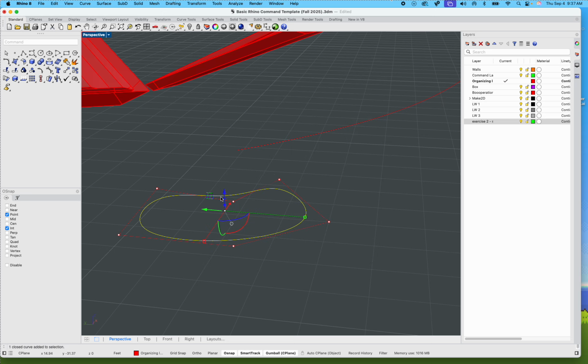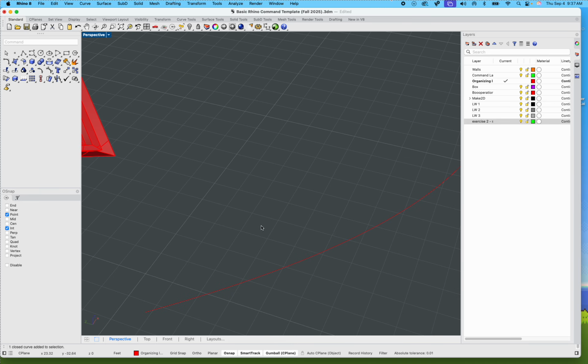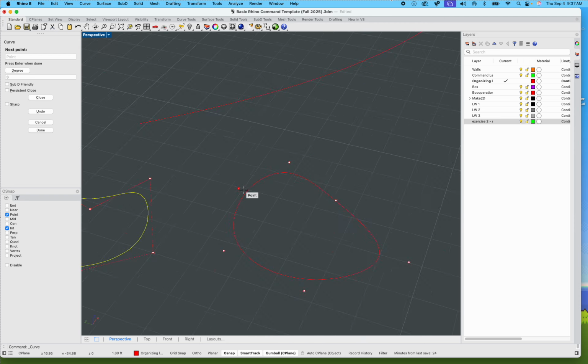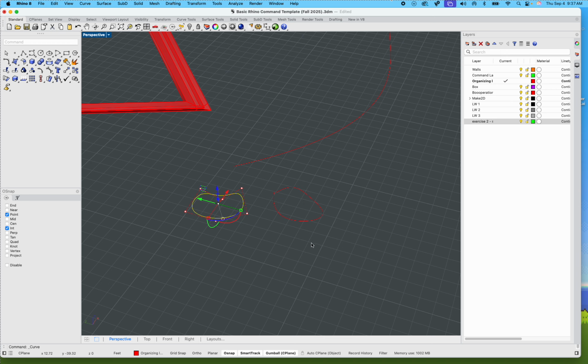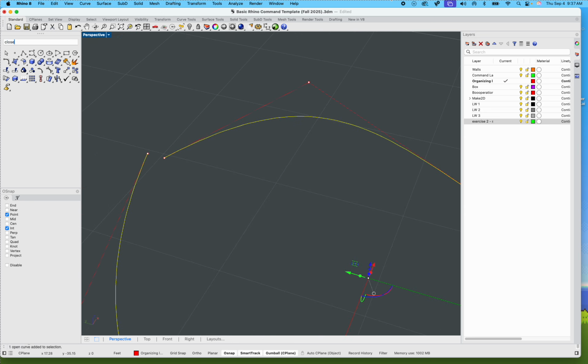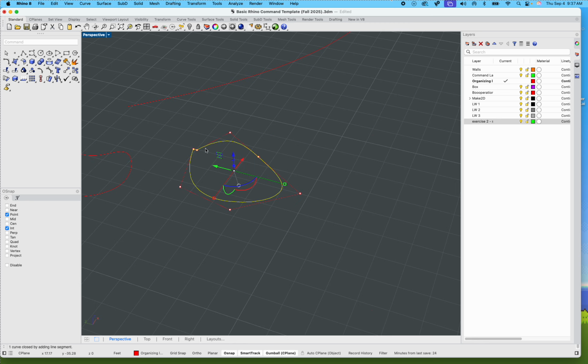But in that case, say something wasn't closed, by the way. Everything's an opportunity to teach, right? If it's not closed per se, let's get that curvilinear line. Maybe I get so close and I think it's closed, but it's not closed. And it looks closed from a certain distance, but isn't. It's not going to work, right? Because it needs a closed profile. However, if I need to fix it real quick, I can put close curve, and it magically closes it for me. So again, I do want to express that because you might run into an issue that we don't necessarily run into in the tutorial.